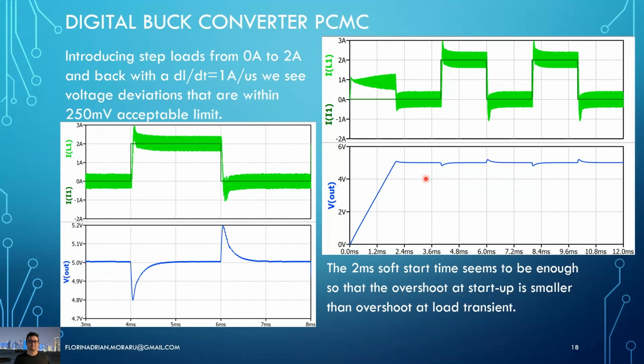Here is the full extent of the simulation time, and we saw that the overshoot at startup is actually smaller than the overshoot we have at load transient. So that means the 2 milliseconds we imposed in the digital controller is enough.